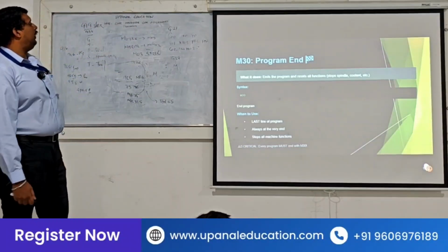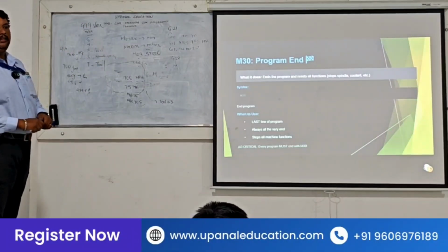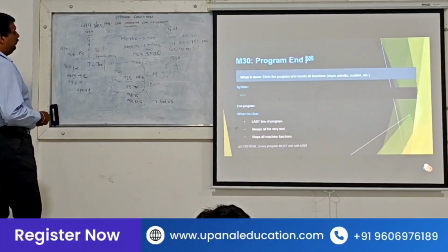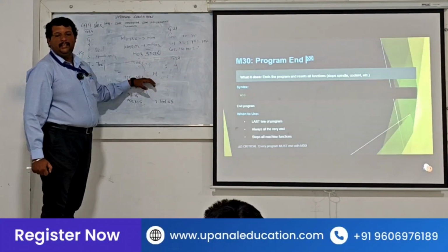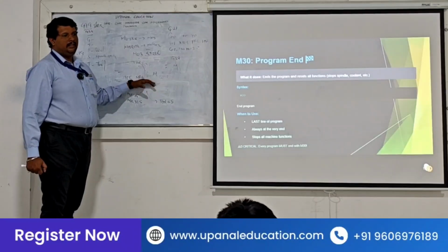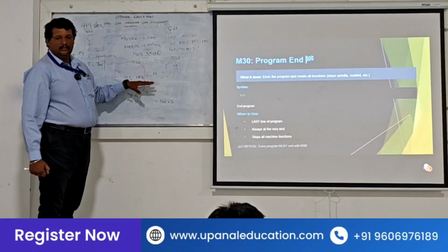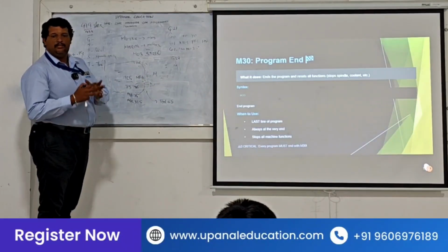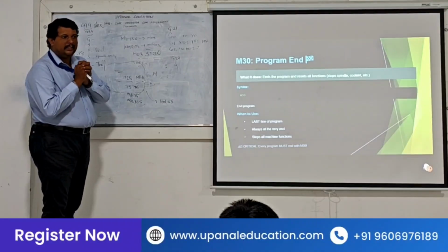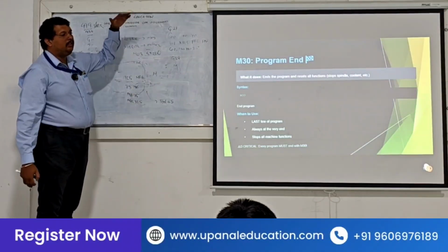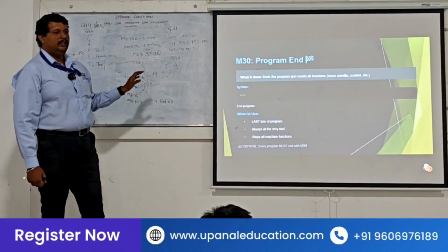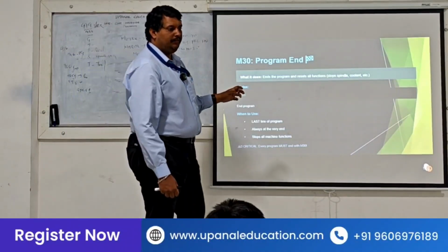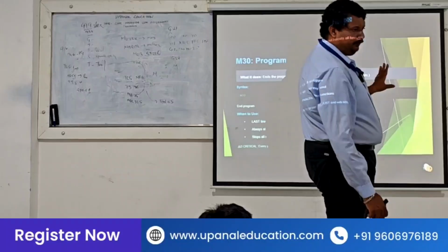Of these codes I told now, only M06 will have a tail, or head, whatever you call it. It will always have a friend with it. It needs a friend. The remaining ones we discussed now don't need anyone with them. They are all individually strong.